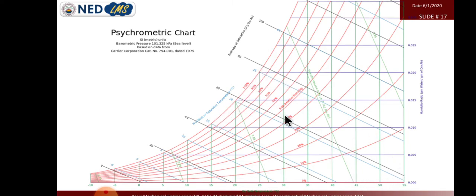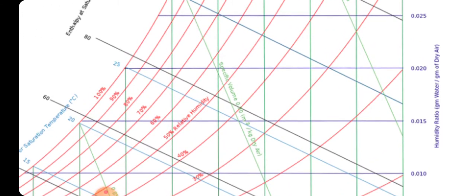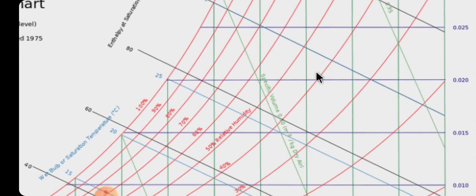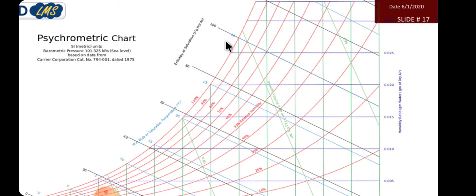This is relative humidity, and this is actual absolute humidity, the amount of water in air, and the unit is humidity ratio, that is gram of water divided by gram of dry air. Let's suppose at this point we have 0.025 gram of water per gram of dry air. Okay, so now you can see that when we are moving from this point to this more desirable point, the